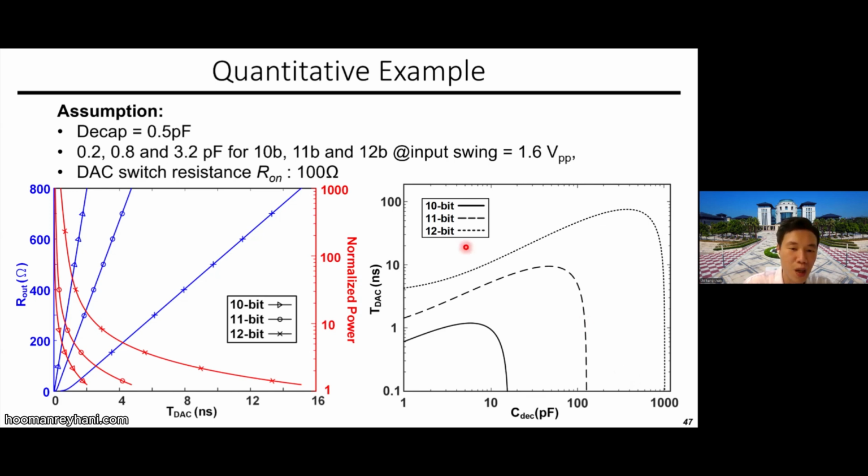Okay, so I would like to remark here, actually this simulation is relatively ideal also, even though we model all the things there. But remember, if you have such a large amount of decoupling capacitance, it is not as effective as in the simulation, because now the decoupling capacitance consumes area and you need some routing to the reference voltage.